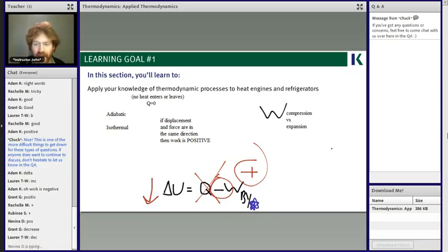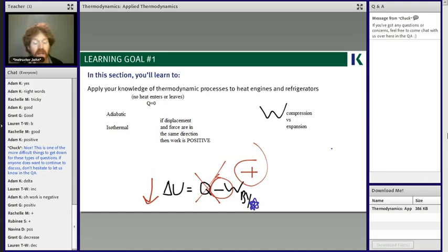Now I want you to think about this conceptually, though, because if you approach thermo from a more real-world life example, it makes more sense. You have two main things when it comes to adiabatic processes. This is actually true for isothermal and adiabatic: if you're not changing one, you must change the other, because all we're going to talk about with adiabatic and isothermal is compression and expansion, right? So there is work every single time. So if there's no change in Q, if there's anything going on with W, it's got to affect the delta U, it's got to affect temperature.